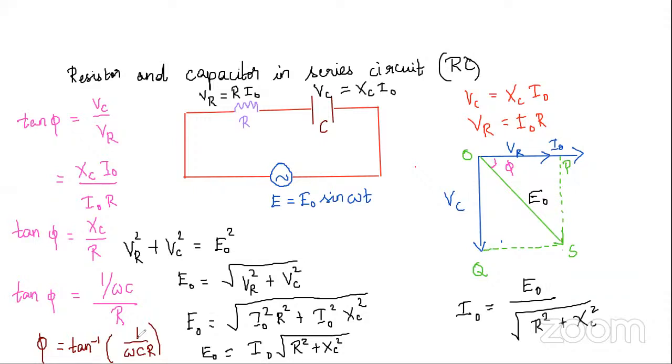And now we will be finding out the capacitive impedance. Impedance means the total resistance in the circuit. Here, the resistance is due to the normal resistor R and the capacitance also. So, capacitive impedance we need to find out. Here it is represented by Z. So, what is meant by capacitive impedance? It is nothing but opposition offered to the AC signals by the combination of resistance and capacitance. So that is given by